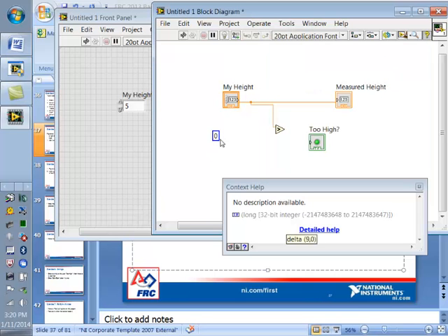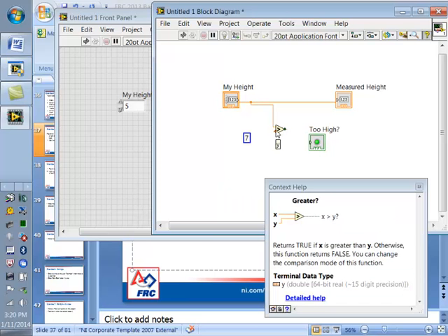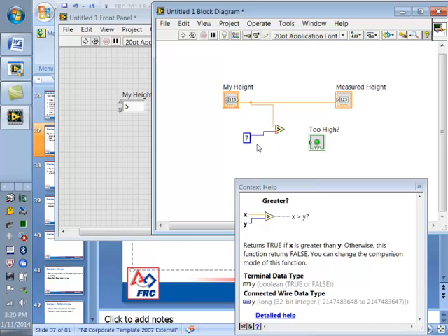So this is now a numeric constant, and I'm going to type in the number 7. How do I do that? Double click, start typing, because I got that smart tool on. Now I've got to wire everything up to everything else. Click, click. So notice I could go backwards. This has got a terminal. If I float over the top of it, it's got a little orange circle and a wire going into it. I click. I can change the direction of the wire.